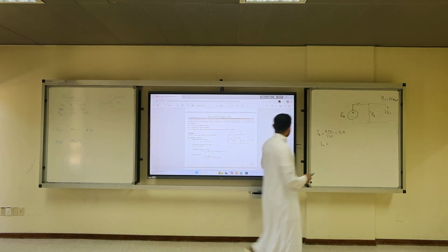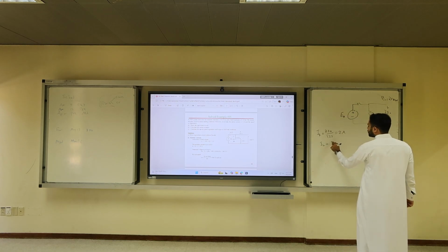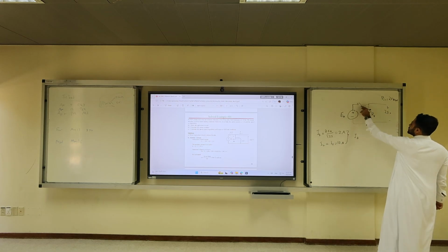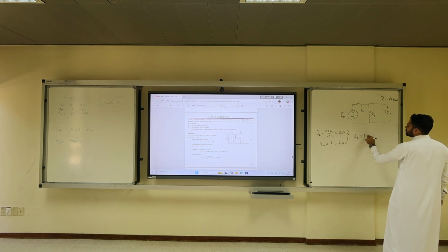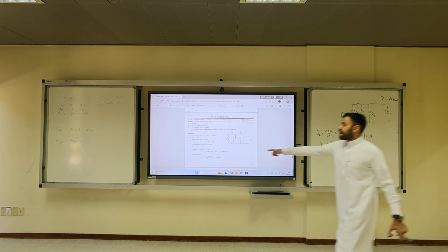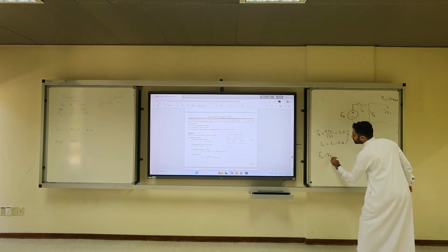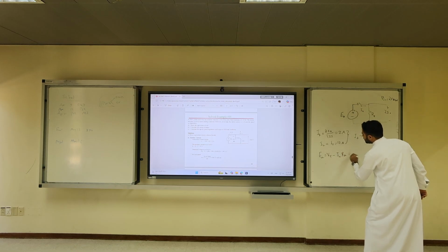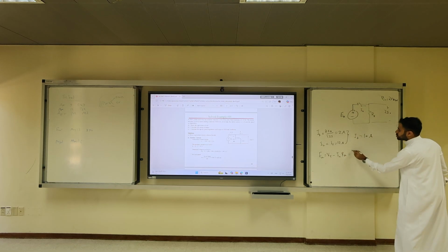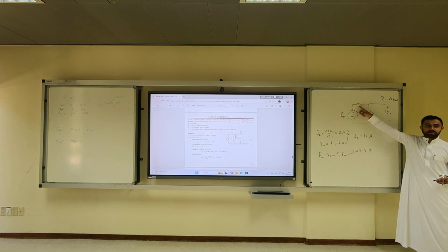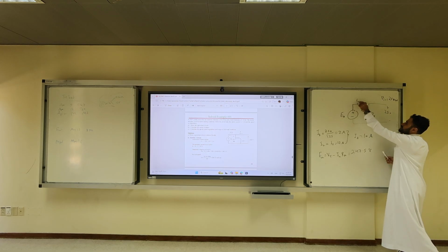Now, I line, or sometimes we call it I terminal, is in the statement 12 amps. So from these two, what is the armature current? 10. Okay? Then he calculated EA. How to calculate EA? It is Vt minus Ia Ra. And if you do the math, you should get 247.5. So this is smaller, so we have a 3 volt drop across Ra, the armature resistance.